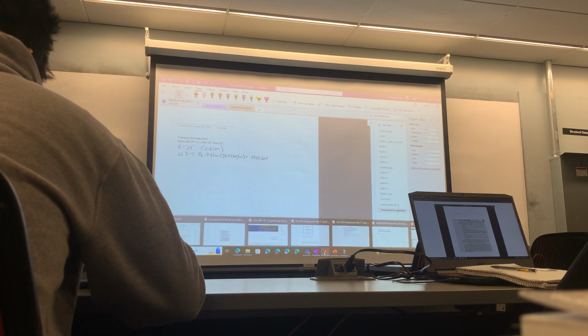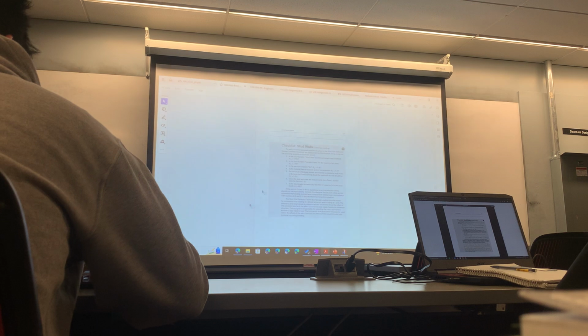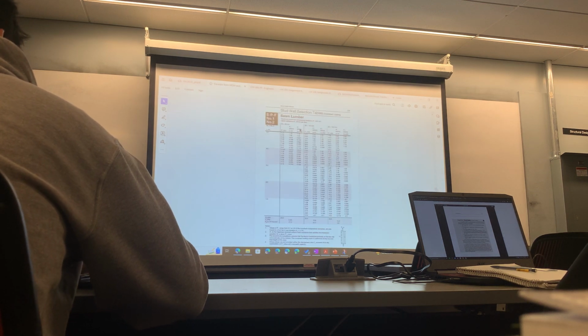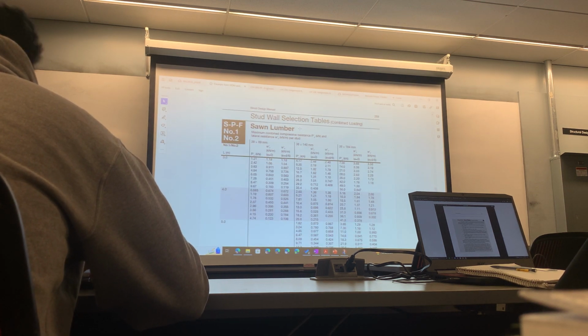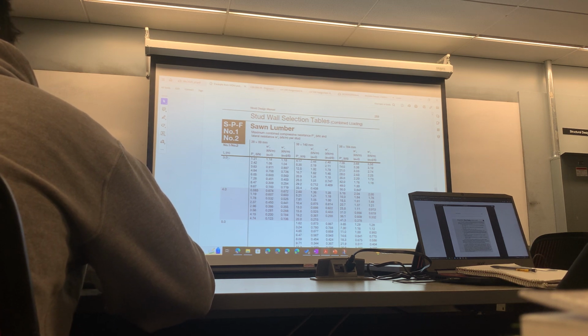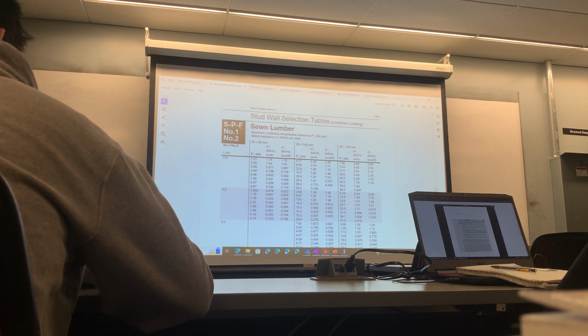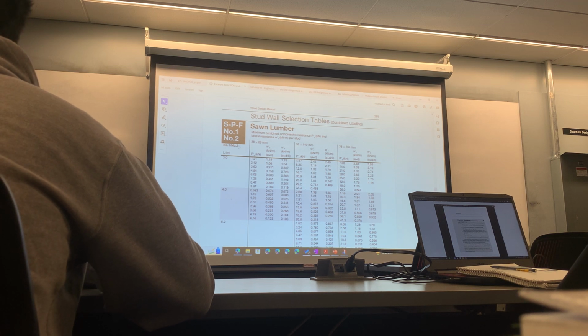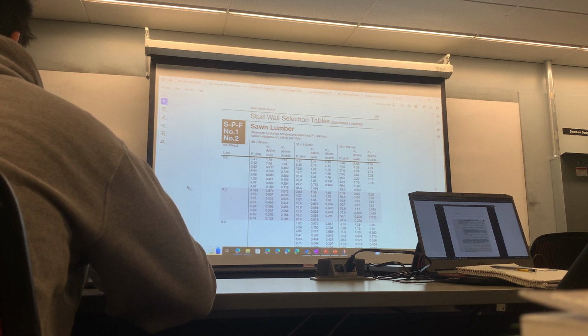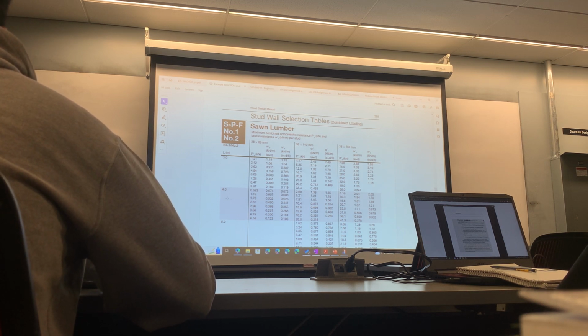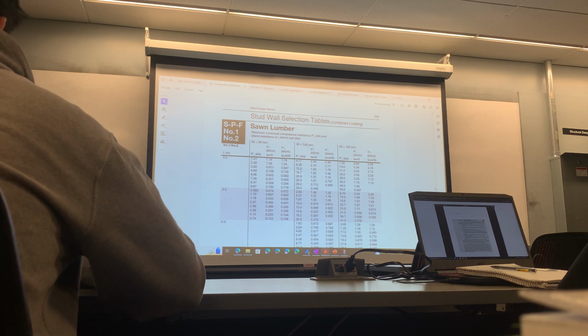All right, so now I'm going to show you the table. We're going to go back to excerpts, and after the stud walls is the table. So it's a little different looking. Right away you have L. What did we say L was? 2.35. So we're going to use a conservative amount. I'm not making you do linear interpolation, so you just take the more conservative one beyond. So L, the next one is 3.0. So up to 3, this will all be the same. For that raked wall, which is almost 10 feet, that's going to be over 3 meters, and then we're starting to come into this region here.